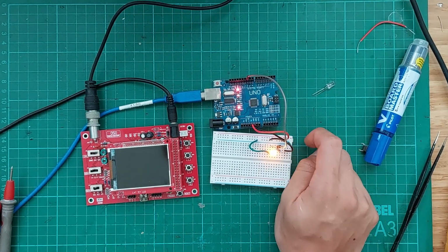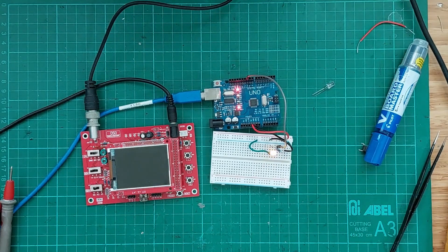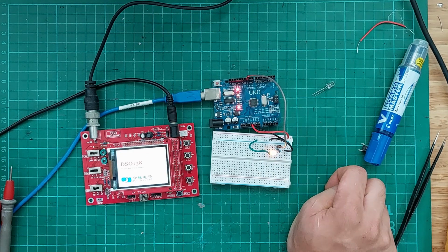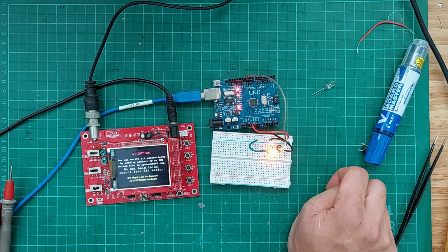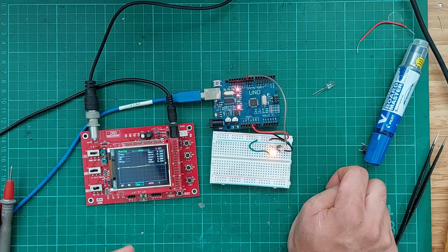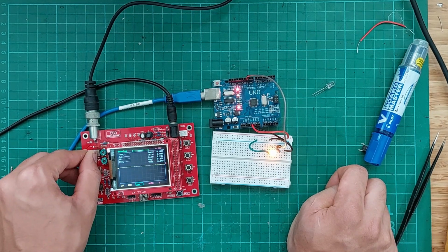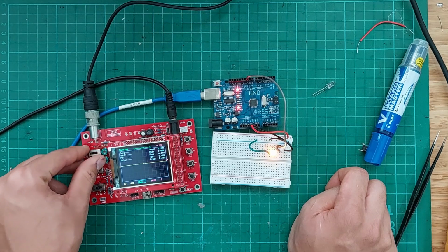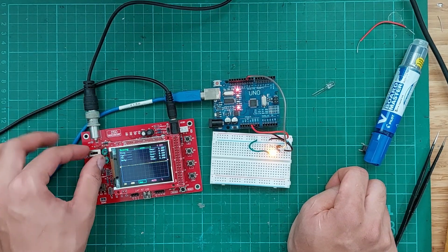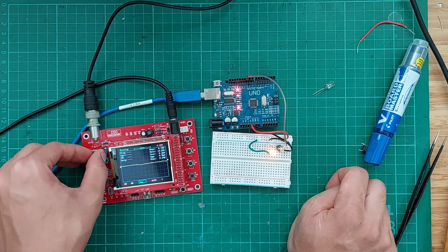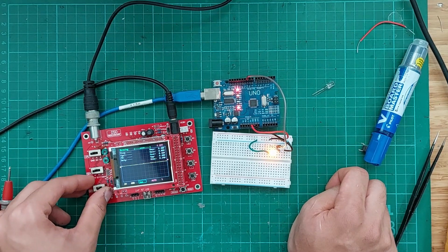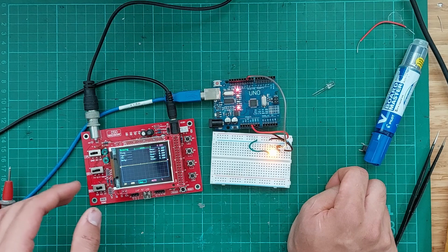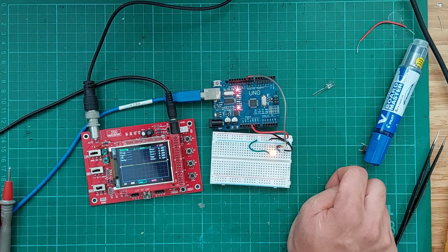So how do we use a DSO? That's not really part of this video, but let's just say that the DSO graphs voltage over time. It shows you the waveforms of voltages, how the voltage of things changes over time. I'll run through a very brief explanation of how to set it. You have ground, which means that this connector is connected to ground. You have AC, which means that it will show both positive and negative. You have DC, which just shows positive, and then of course this sets the resolution. The higher you go, the less detail you see, but the more things you see.